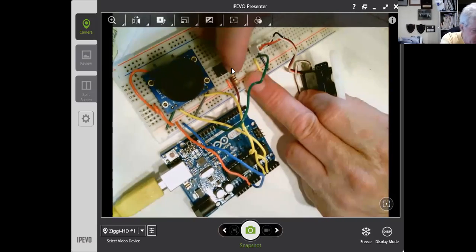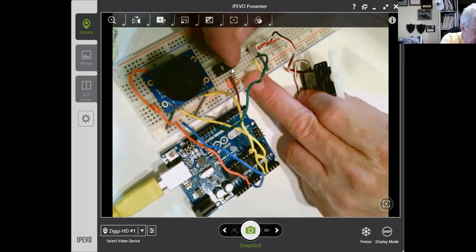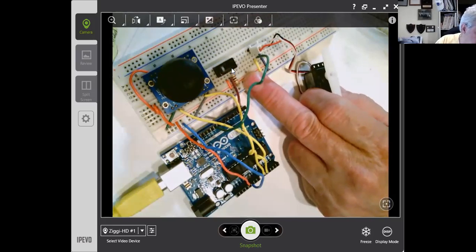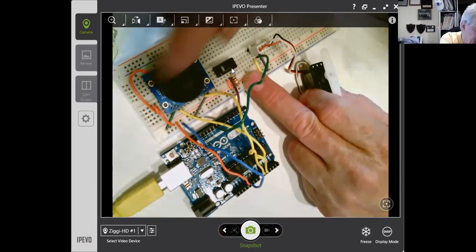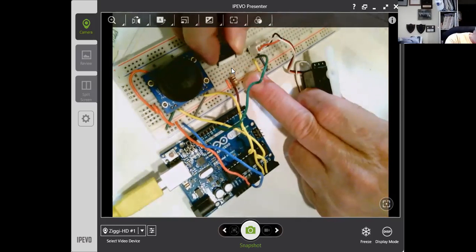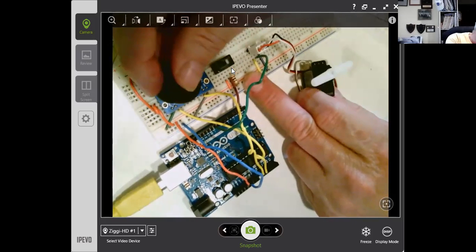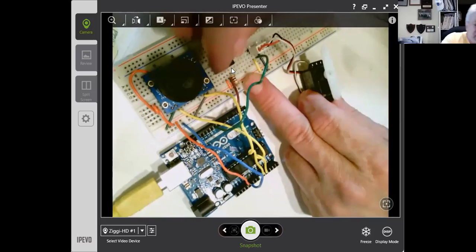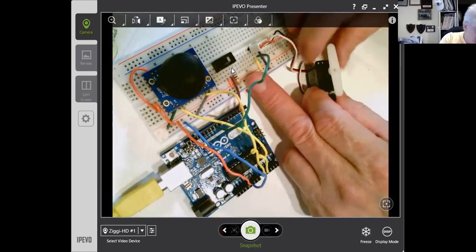Okay. So with the switch pushed towards me to the far right, the middle pin and the pin on the far right is basically connected through a 100 ohm resistor back to pin 3 of the Arduino board. It's pulling in a 0. And if I leave that there and I move the, actually I have that disabled, so just ignore that fact.